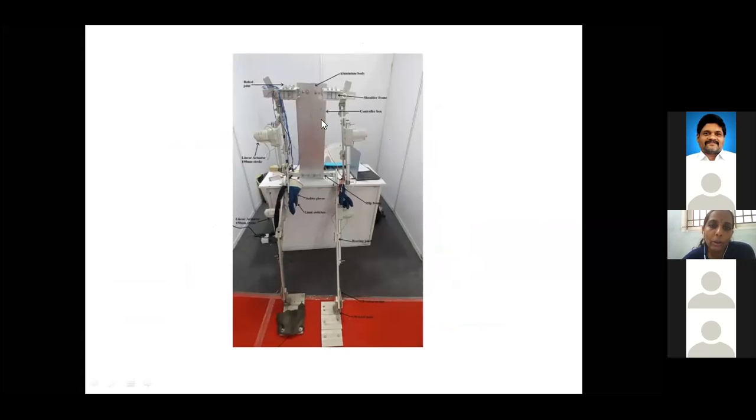We have developed this with the help of aluminum bars. With the help of linear actuators we are able to operate it. You can use servo motors for these joints also. This linear actuator has 70 newtons of capacity, and it can withstand weight up to 100 to 150 kgs. You are able to lift the maximum weight, but the main disadvantage of the developed exoskeletal device is that it weighs up to 26 to 27 kgs.